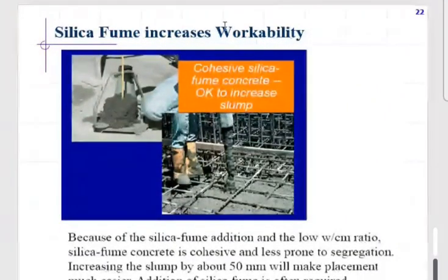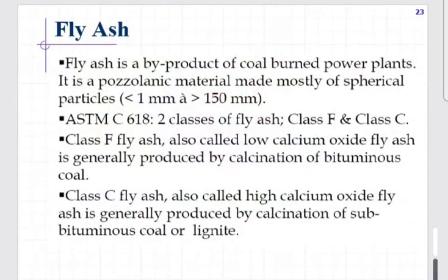So we cannot say this straight away that every time you see silica fume it is going to, but however, if you see your porosity is being reduced and your mix is consistent, you may observe that your workability is being enhanced. But for the same water cement ratio, if you want to make it workable, you may actually need high range water reducers to improve the workability. So are we okay with the silica fume, students?